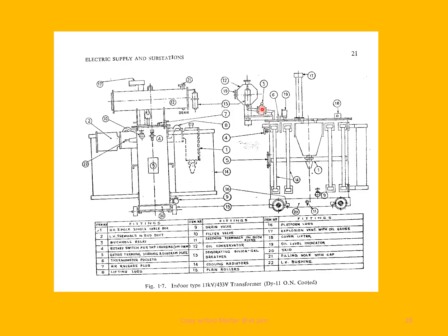So the Buchholz relay disconnects when there is a very large amount of vapors produced in the radiators. So this is a safety device, Buchholz relay.